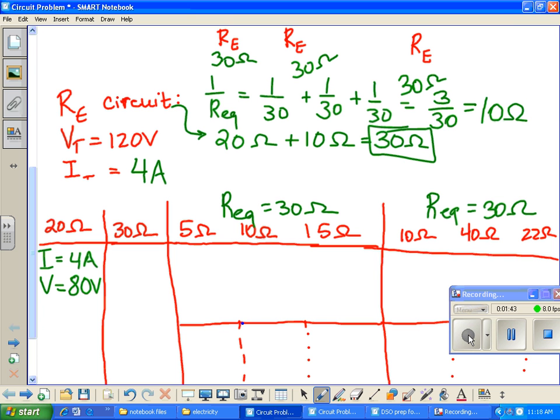When I look at my circuit, I should notice that now I have 3 options. If I choose branch 1, branch 2, or branch 3, I will have to spend all the remaining voltage at any one of those branches. So I could do a subtraction problem. I start with 120 volts and I end up spending 80. So how much voltage will I have to spend at any one of those lines? What's 120 minus 80? So each line I must spend 40 volts.